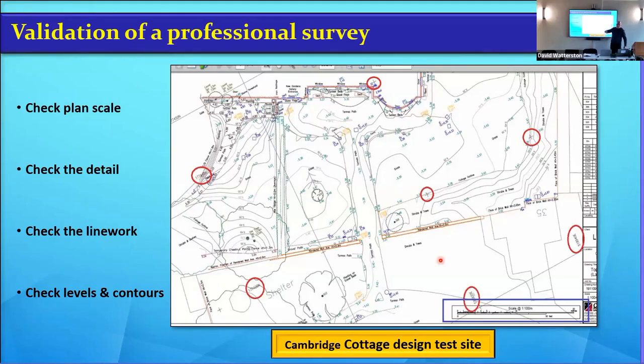So you can either use the floor level in there if you can get access to it, or you can use the DPC, which should be the same around the house until it changes direction. But the trouble is, if we're going to design all this and then put hoarding up around the house, you can't use your datum level, which is not a good thing then. So if you have based it on your floor level or DPC, you want to then use it on a manhole or an IC, or certainly two or three other places that you can give it, which is a temporary benchmark, which you can use. If that's got hoarding over it and you want to do more levelling, you can't use it from your base point, you can use some other datums that you've placed. So it's a good idea.